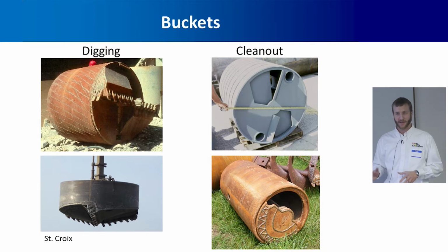Now, it's called a clean-out bucket, but if a contractor tells you that a clean-out bucket is fully sufficient to clean the hole, that's generally not the case. So if the contractor tells you that, be wary.